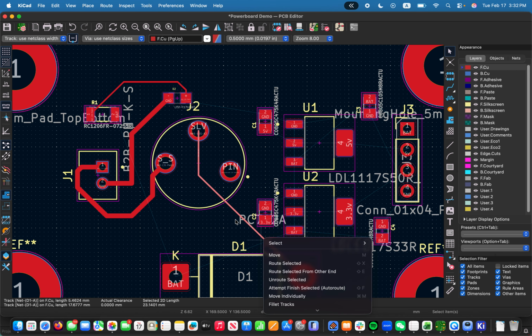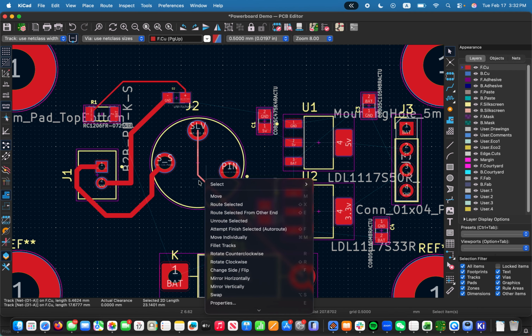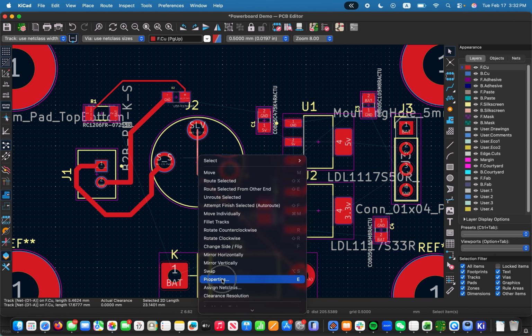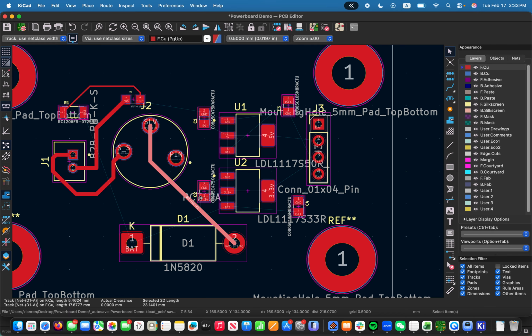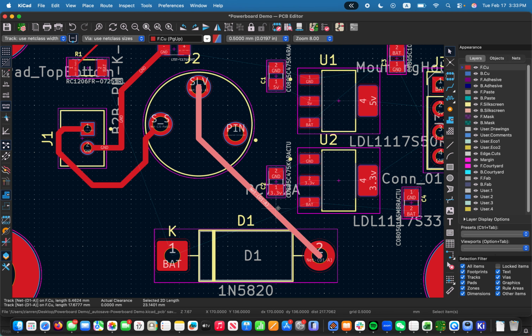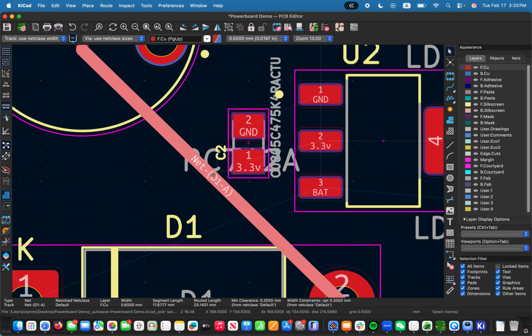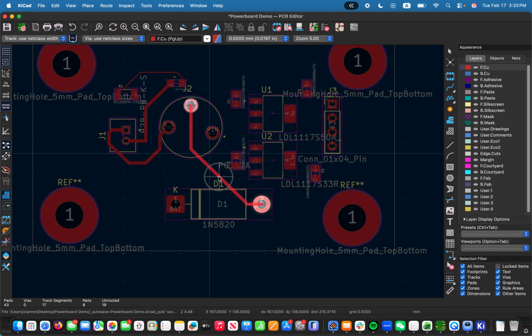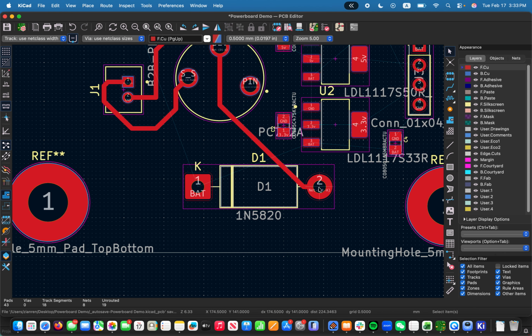And this is generally a good practice to make your power lines thicker, because there's just more current and voltage running through them. And since this is a power board, we want to be really careful to make everything work. And then you see here, that's a little close for comfort. So I'm just going to click, and then I can drag to change how those traces are. So then this is a diode. A diode allows one direction of current flow. So the current will only flow this way. Only flow this way.